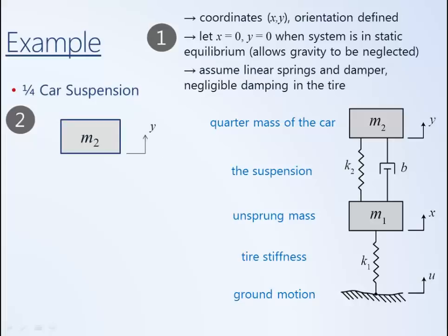So I imagine that mass 1 is fixed, and if I move mass 2 in the direction of positive y, that stretches the spring, and so it's going to want to pull down, and so I orient my spring force to be downwards.